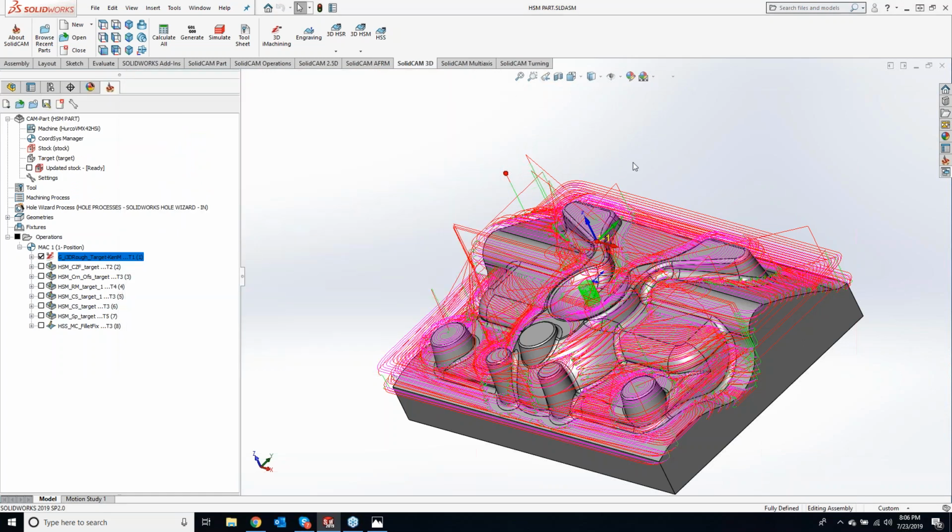Like I said, I try to use the 3D iMachining absolutely as much as possible. Even for our prismatic parts, I will try to use 3D iMachining to go through and get all that material out of there, even though that's still going to leave 10 thou or 15 thou on your wall and floor. You guys can always come back and finish that up. I think we talked about this a couple of years ago, where on prismatic parts or 2.5D parts, you guys can actually use a full 3D tool path just to make it very easy.